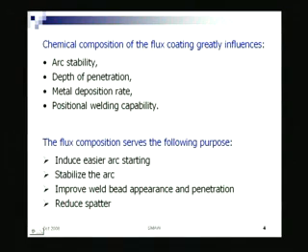Current flows means what? Flow of electrons takes place, or bombardment of electrons takes place. In the process, heat is generated in that plasma column, right. That heat then keeps on melting the metal as well as the electrode. Now, that will keep on melting provided the arc is stable. If the arc gets extinguished, then there is no heat. Again, you will have to strike the thing, create the arc. So, that is what arc stability is. That means a stable arc will give you a stable heat.